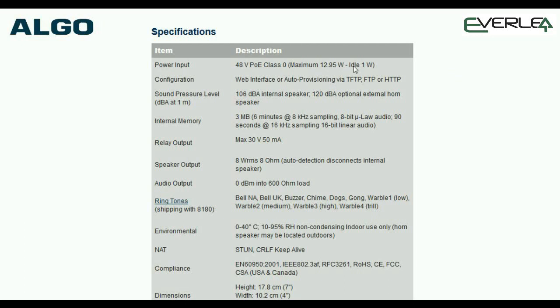A lot of the PoEs aren't created equal. Some of them say, well, I've got a 60 watt maximum power allowance, or a 55, or an 80 watt, or a 70 watt, or 120 watt. When you're deploying voice over IP, when you're deploying voice over equipment full stop, please be aware of what the maximum loads are of each device. Otherwise, you could overload the device to the point devices could fail.